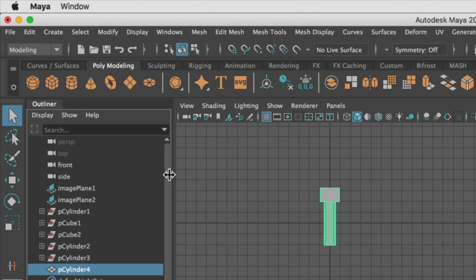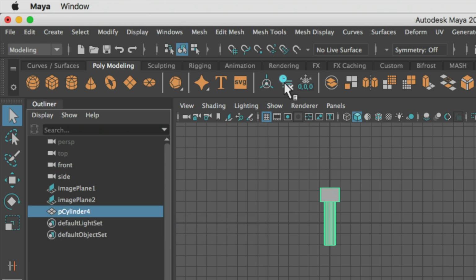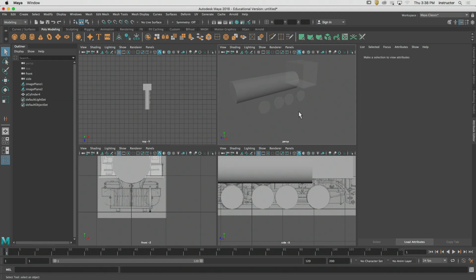And the first thing I do when I combine it, see all these things with the little red arrows? These are references back to the original independent mesh objects. We don't want those references anymore, so deleting the history will remove all that stuff. Okay? Because remember, Maya keeps object history on everything, even combined. Every operation that you do, Maya is going to remember. Often, we want to disassociate this object from its past so that it's independent and can move forward into the future cleanly. Right?